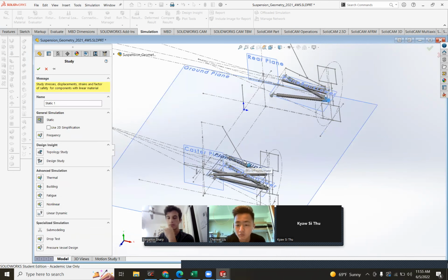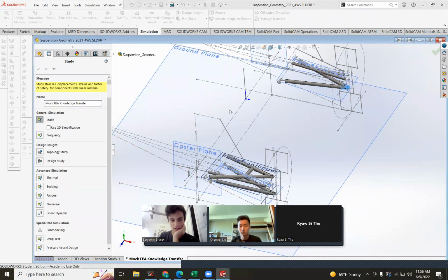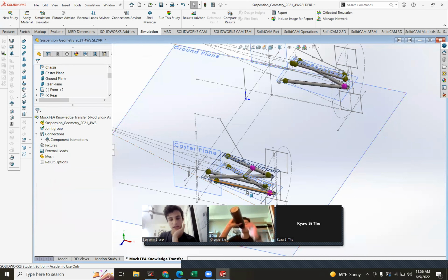So the reason that the arms are tough to FEA in SolidWorks is that it wants to treat them like tubing, which is a different solver than parts. It's not treating the arms as if it were an aluminum part or a steel part. It's treating it as a simple tube, and there are way too many assumptions in that method. It's very inaccurate, and it doesn't want to mesh very well.